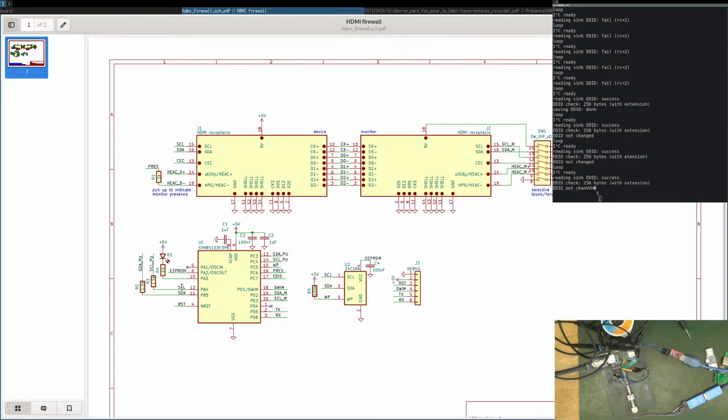So to actually test it, what I could do is not pull this low, because if I pull this low, we will have a voltage divider between this one, and this line might not be low enough for this to be detected low. So what I will do is pull these lines low, SCL and SDA, and then I will check if on this side they are also high and low. And based on that, I can figure out if they are forwarded or not.